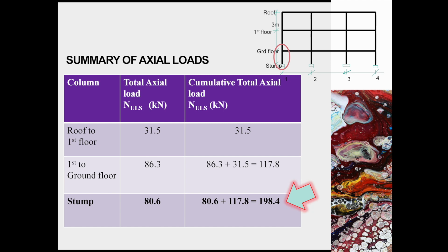To wrap up, the area method is very useful but gives only a rough estimation of loadings for columns. The designer may need to use the method when the foundation information is needed before the detailed calculation comes. The designer needs to always make sure that the axial forces obtained from this method are double-checked once the detailed calculation is ready.